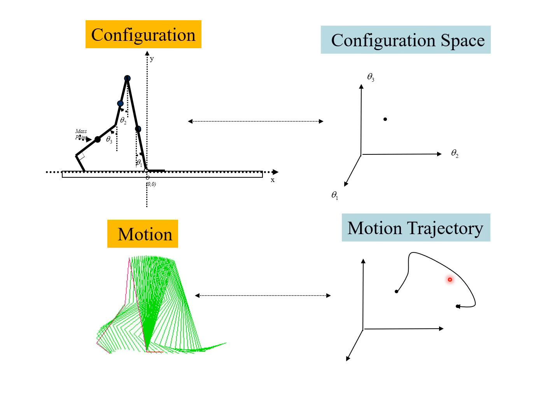Now, if you have this trajectory as theta, you can take the derivatives and you get the velocities. Derive it again, you get the acceleration. So that's a kinematic analysis of the human motion structure. Does that make sense of how to do this? So this is all about step 1, which is doing the idealization, looking at the ranges of motion, maximum, minimum, and thinking how it is going to move.